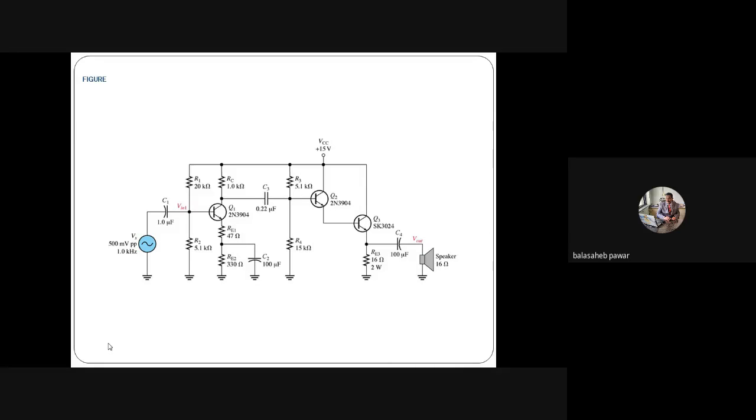When we decrease the input signal amplitude to a particular level and below it, we will observe that the amplifier circuit is not working as an amplifier. That means the output becomes noisy, corrupted. Right? So for example, if this first stage does not support a 100 millivolt peak to peak signal.